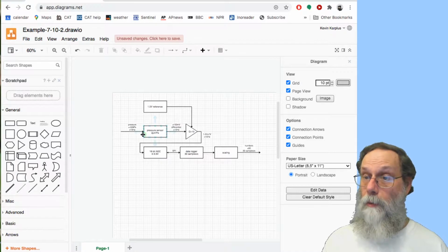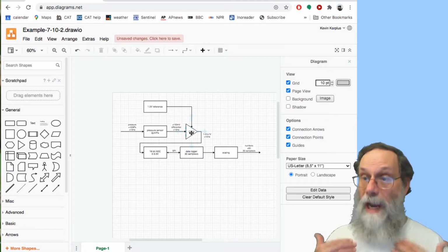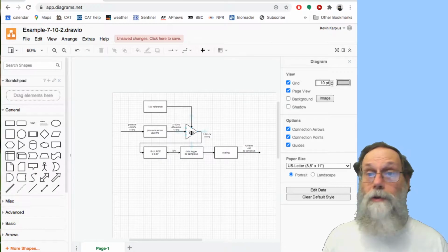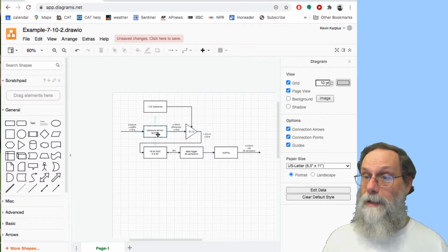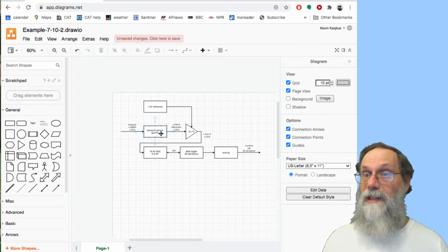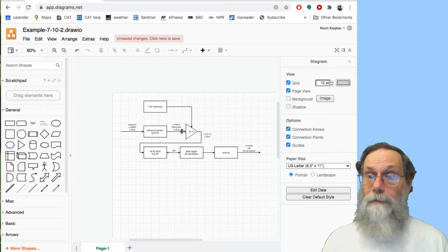In fact, one of the things I do when I'm grading design reports is I go through the block diagram and do a consistency check on each block. And if it's not consistent, if you'd said the gain is 20 here, I would know there's an error in your design, a serious flaw. And you should be able to find those serious flaws yourself too, just by doing a consistency check at each block. Does the function of this block match the input and the output? Is there enough information to be able to determine that? Is the sensitivity here consistent with the range of the pressure coming in and the range of the voltage coming out? That's the sort of check that block diagrams enable, and you should be doing them.